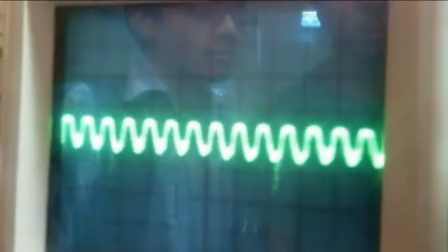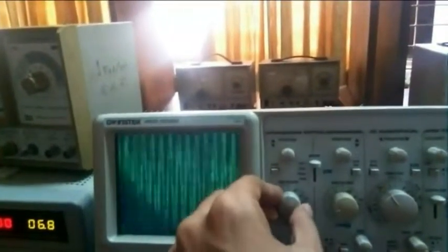As we change the frequency of the sine wave, we can see that the signal is changing at the output oscillator signal as well as the pitch of the sound. Now we are changing the amplitude of my input signal, and on the output stage we can see that the amplitude is changing as well. And at the final output amplifier stage, the gain is as shown.